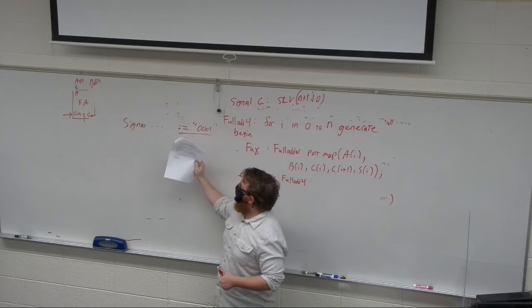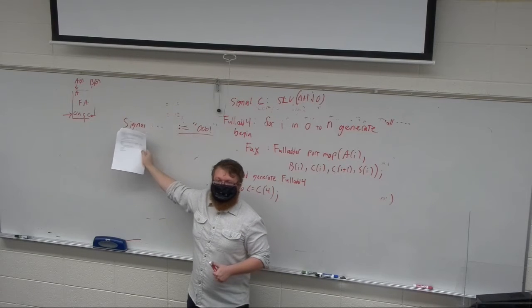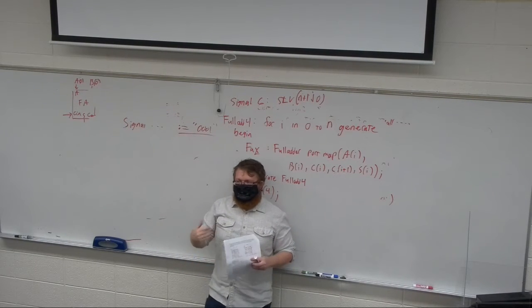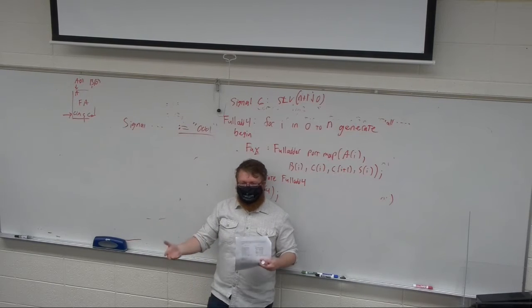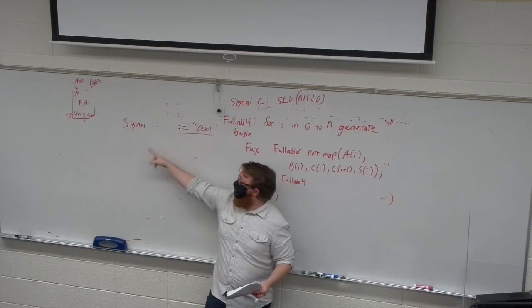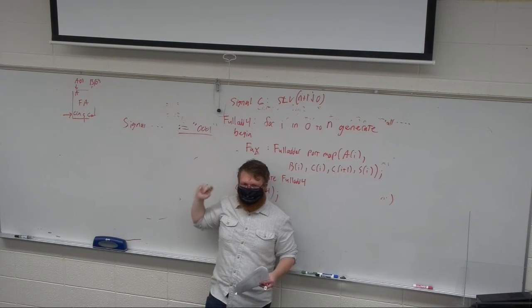But if you don't change it, it'll just assume you entered a constant and create it as a constant, which works just fine. The time that I know it never works is in VLSI. When you're writing code to make an ASIC, this will never work. If you call it a constant, it's fine, but saying it's a signal will get confused and be disastrous.